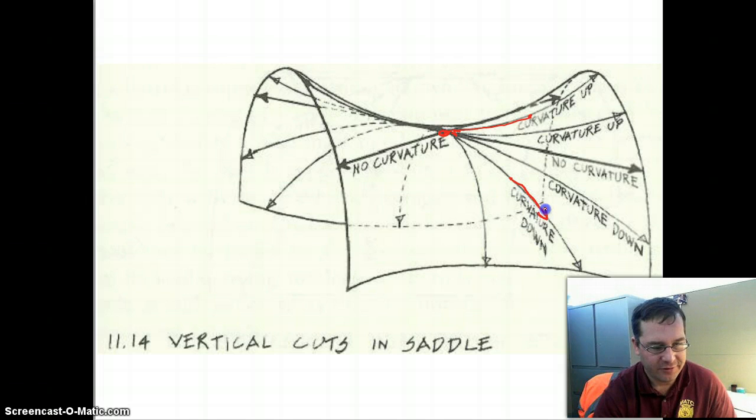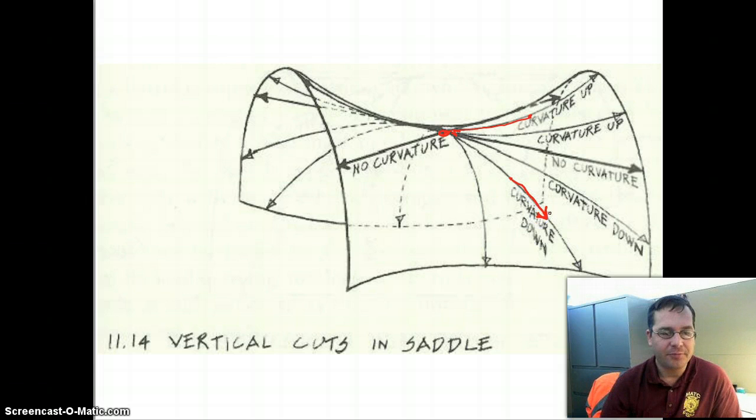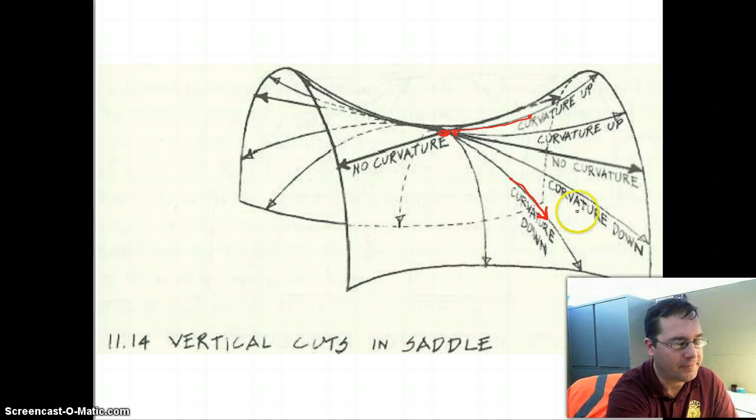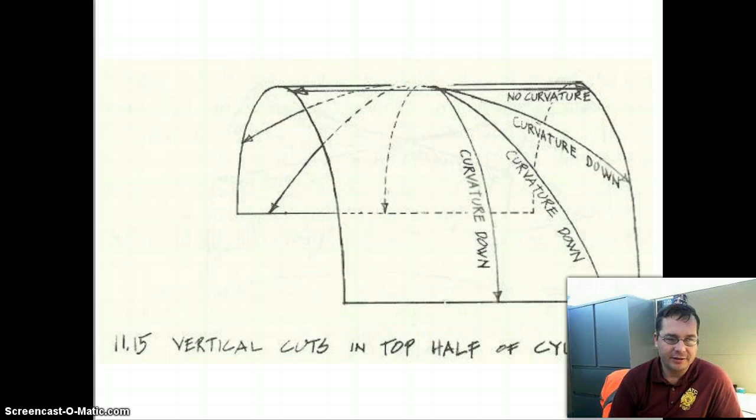So the saddle is an interesting shape because it combines a number of curvatures, and it's an efficient shape because we're able to use all of the characteristics of the material: strength in compression and strength in tension. And again, it's a non-developable shape. So typically these would be constructed of cast concrete, which is an effective way to produce a complex shape like this.